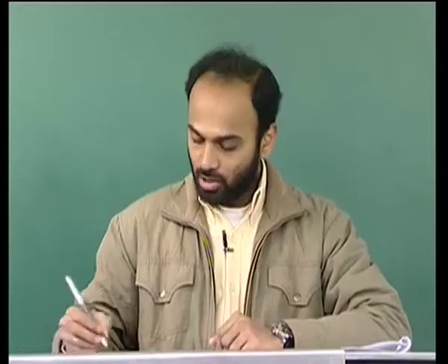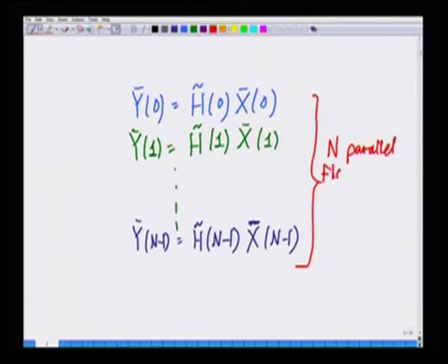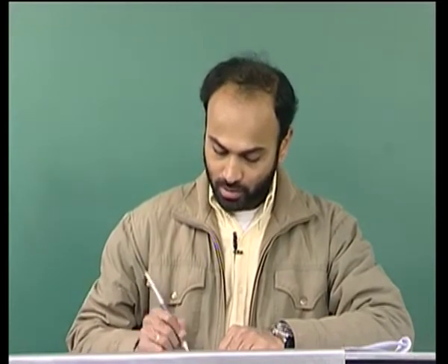Alright, since this is MIMO, we have multiple transmit antennas as well as multiple receive antennas. So, essentially this is nothing but our set of n parallel flat fading MIMO channels. And now what we can see is each y bar 0 can be simply processed by the MIMO techniques that we had seen earlier, which was the MIMO zero forcing receiver or the MIMO MMSE receiver. Let us just, to complete that discussion, look at that.